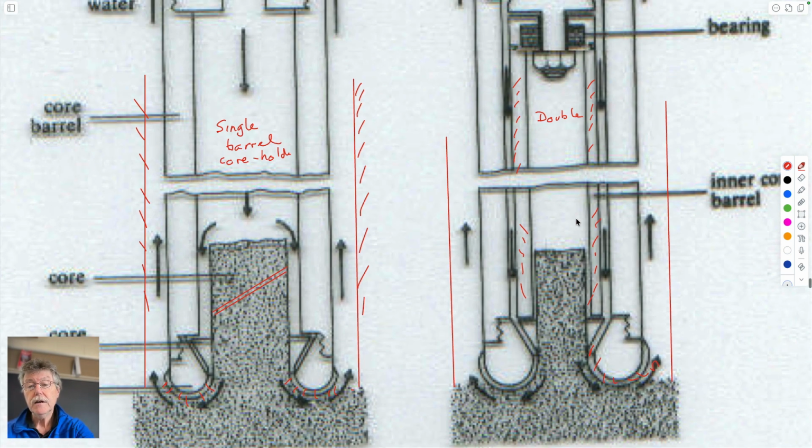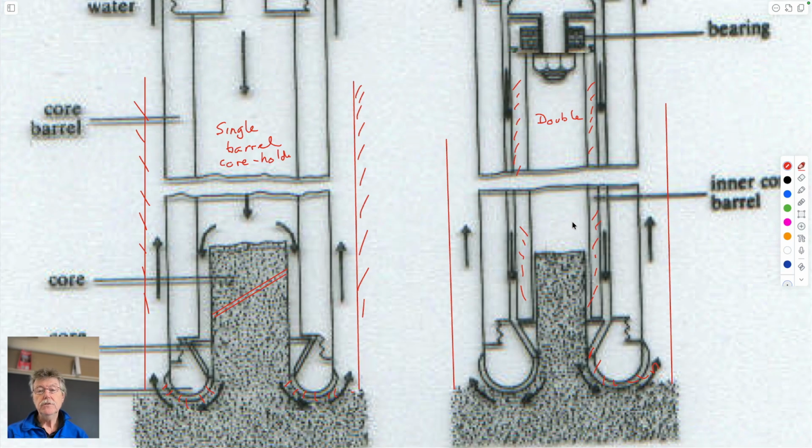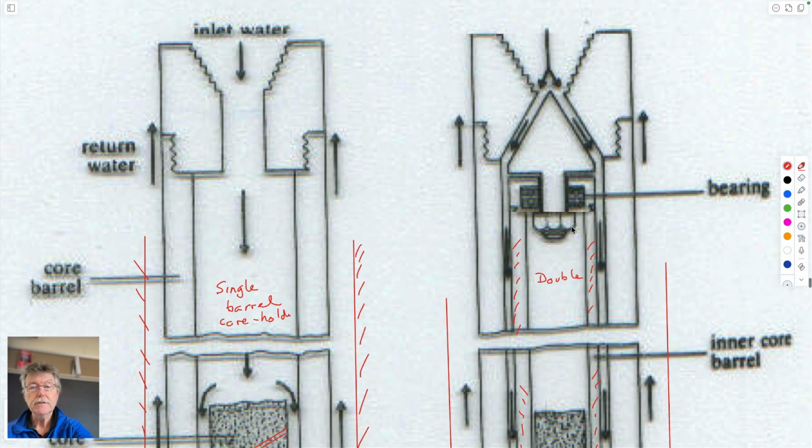But also, what you can do is you can use a wire line to sample this. And so the idea here is that the drilling fluid is coming down here, it's diverted around the inner core holder, so it doesn't touch it. But when you get down to the depth where the core has risen up completely within the core barrel, you know how long your core barrel is, 6 feet, so you know you can advance 6 feet beyond the bottom of the hole when you're drilling.